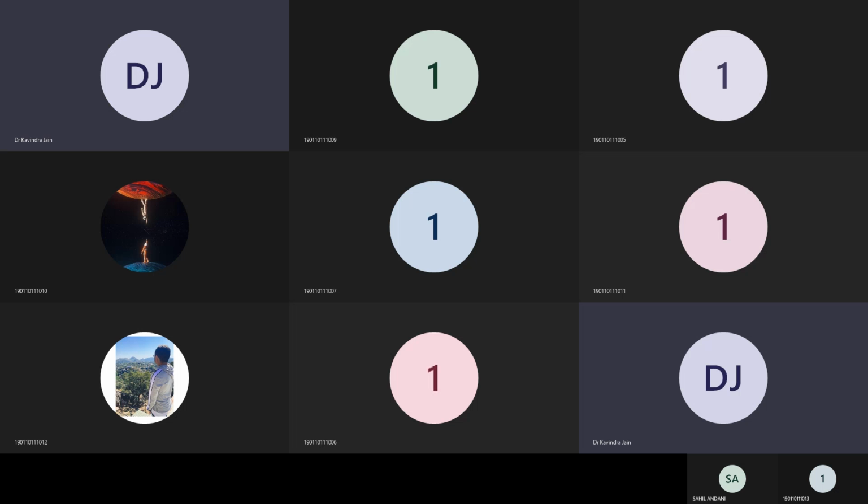Thank you guys. That's all for today's introductory lab, where we discussed the data sheet of 741. Along with the data sheet, we have understood how we are going to perform the experiments. Those who are new to the lab may please note down what has to be written in your experiment number 0. I repeat, experiment number 0. Experiment number 0 would be the datasheet reading of LM741, where you need to attach a single page briefing the pin configuration and the constant values of LM741, that is the practical values along with the ideal values, a comparative table of practical and ideal values of LM741, in your experiment number 0.